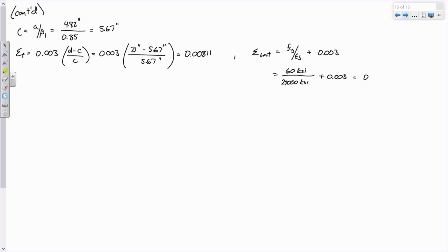0.005. Do I have a second on that? I think it maybe comes up like 0.0507 or something like that. But from the slides, you said it 50. Yeah, 60 grade steel, you assume. I'm glad you remembered that. That is exactly right. I was getting ready to say that. If you're ever dealing with grade 60 steel, this comes out to like 0.00507. So you could say the strain limit for grade 60, you can just take that to be 0.005. See, the spec actually used to have that as a constant for any steel. But now they're a little more refined with it.